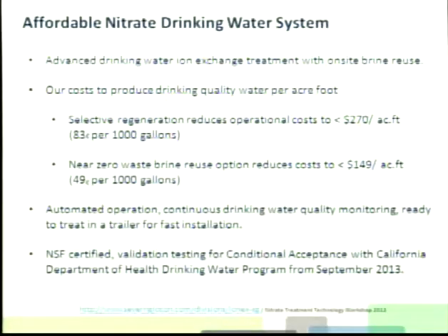And we have two methods of reducing the operational cost of ion exchange. Our first one is that we look to optimize, especially the removal of the competing anions that Chad eloquently put just now, is to look at selective regeneration, which we've done on full scale on public water, drinking water treatment systems in the UK, and that we can reduce the operating costs by stopping the sulfates and the bicarb fraction of the eluted regenerant from going into the truck that goes to the waste.